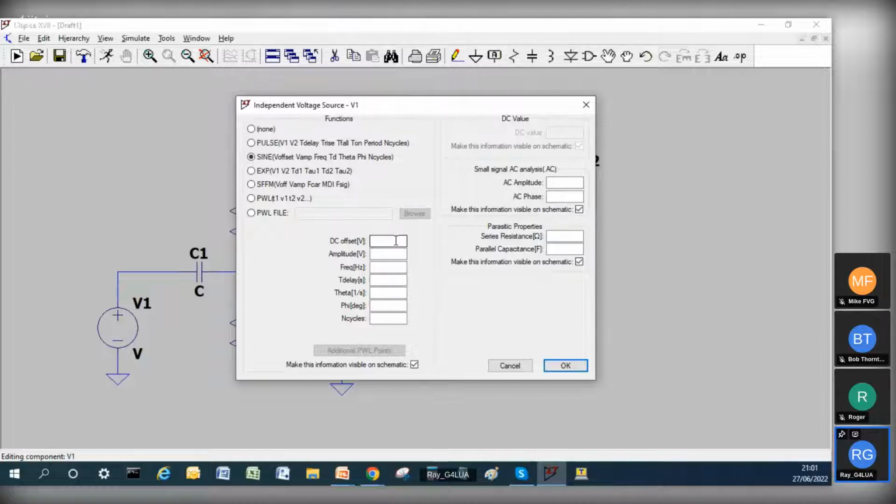You can set the amplitude. Let's set that amplitude to 50 millivolts. You don't have to put the whole millivolts in, but you have to put M in, a small m. If you put a large M, it's accepted as mega. You have to put meg, M-E-G, with a large M to distinguish. So we'll come to that in a minute.